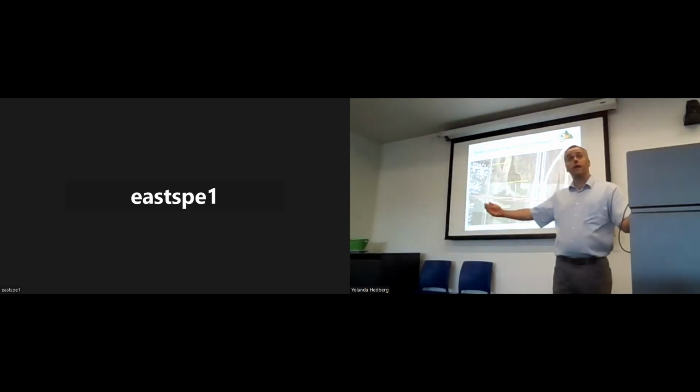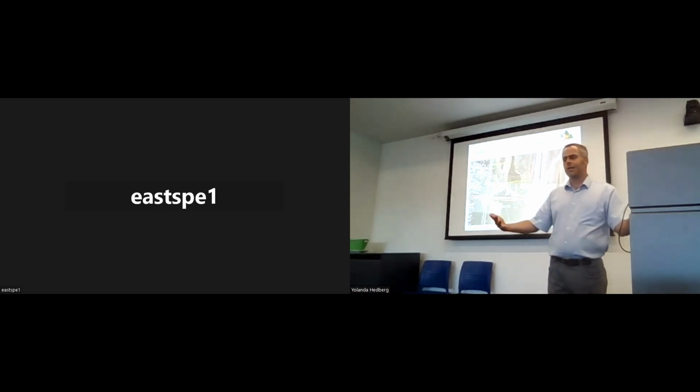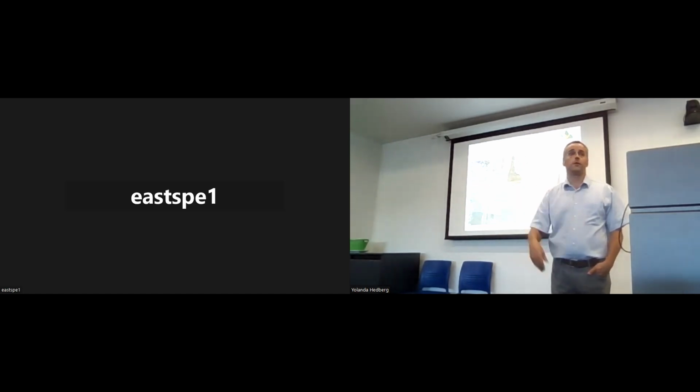But you do not always know these kinds of sources, right? You don't know. Yeah. So what's important to note here is we did our survey, we got our data, and we're looking at the data, and we're like, something's going on there. Well, then you go to site, you walk around, and you're like, oh, there's a ground bed right there, and it's not ours. It's affecting our readings, but it's foreign to us. Okay? So what can we do? We can bond to them. We're part of the same CP. What we actually did is we put in a supplemental CP hotspot to increase our potentials at that site.